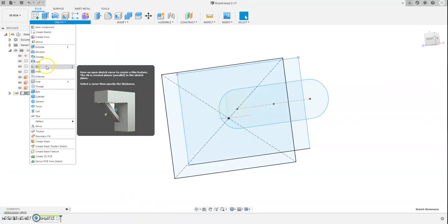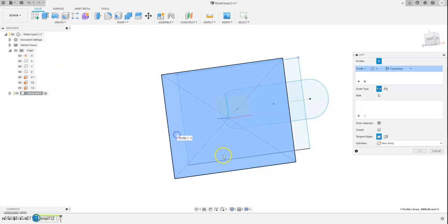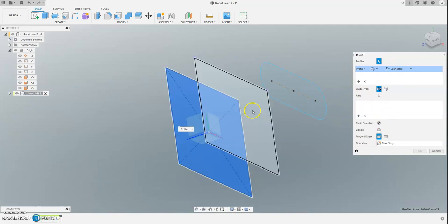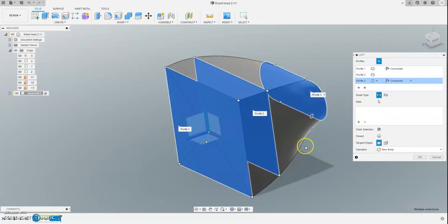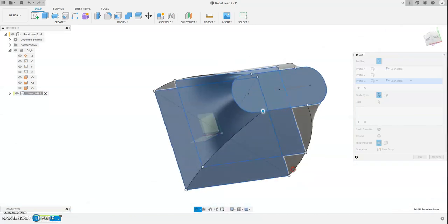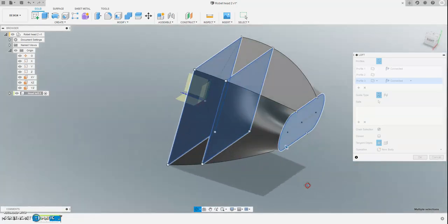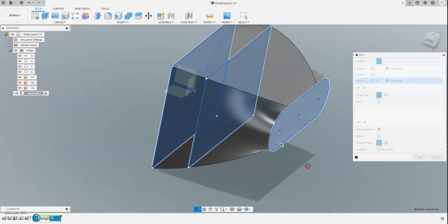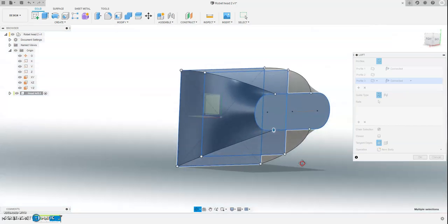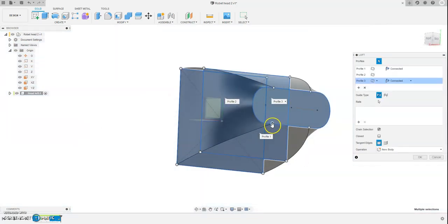So my loft, I'm going to loft from this surface. Now it brings up this menu manager and it lets me select the order that I want this to go into. So when I select it, it automatically generates the loft for me. Now if I have a little look at that, I'm quite happy with that. It's quite a nice little sweeping loft in there. It has all these options that I can go for with guide rails and everything like that, but we can look at that in a different video.